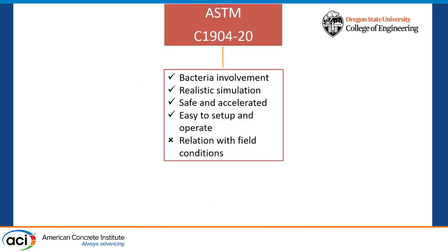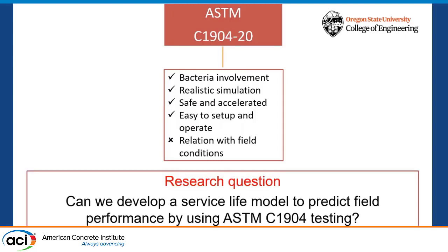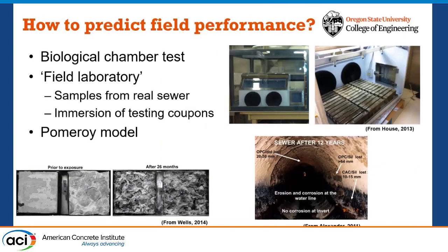So we have a recently developed test, ASTM C1904. This test has bacteria involvement, so we can say it's a realistic simulation. It's safe and accelerated, and it's really easy to set up and operate. The only disadvantage here is that we don't know the relation with the field conditions since it's a new test. So our research question here: can we develop a service life model to predict field performance by using this ASTM test?